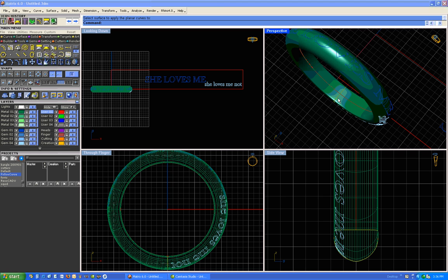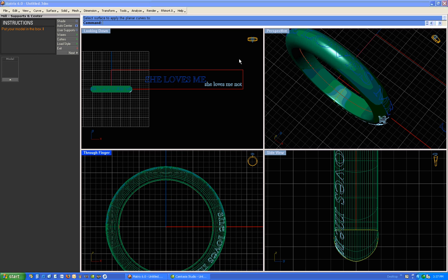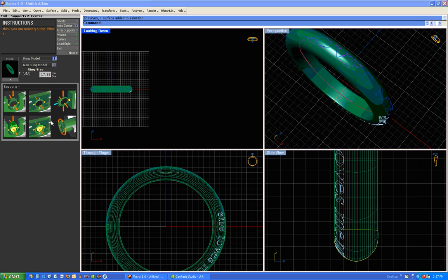Assuming that the text curves are now just what the customer wanted, enter into the Revo Builder. Curves on the outside of the ring will be milled as part of a rotary job on a tube of wax and 3-jaw chuck, or as part of a rotary job on the center hub fixture. Let's do the rotary job first. We click No Inside Work.